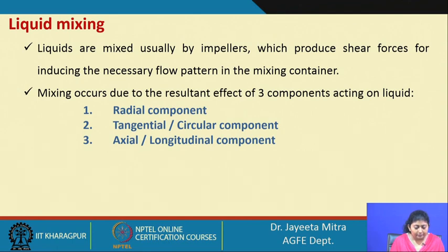Now, mixing occurs due to the resultant effect of three components acting on the liquid. One is the radial component, another is the tangential or circular component, and third is the axial or longitudinal component. Okay. So, components of what? Actually those of the impeller that is rotating. Because of that the liquid will have a direction in all three ways, either radial direction, tangential direction or axial.